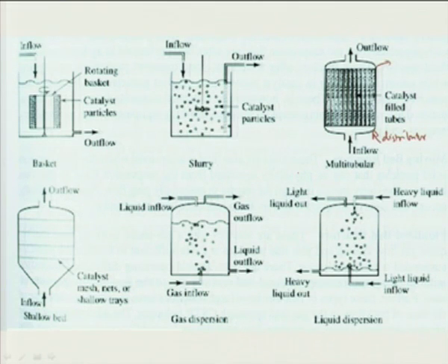Then comes the circulating flow reactor. The circulating bed, which I just mentioned, is like the moving bed reactor. These are essentially the same as a fluidized bed reactor, but they create suspension of particles through fluid impingement. In some cases, spouted bed reactors are used, where the reactant flows through a shallow bed of catalyst particles and lifts the catalyst particles slightly so as to create more voids or more mixing.